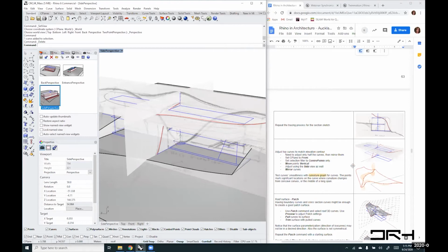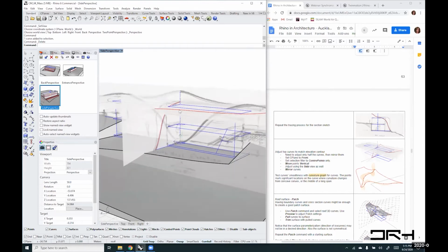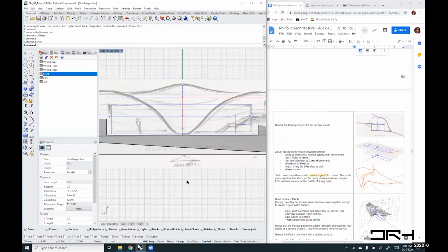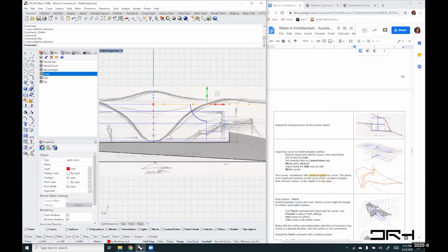As you can see in the handout, I need to adjust my curve to be following roughly the contour of the front now. So I'll need to move the control points down a little bit and adjust them for the top curve to be aligned vertically. So I'll change my C-plane to be front and go plan view, right? And this will help me move these curves vertically, following this.